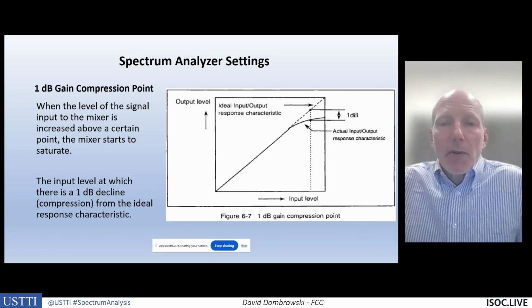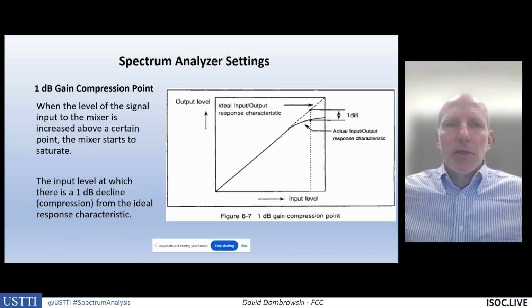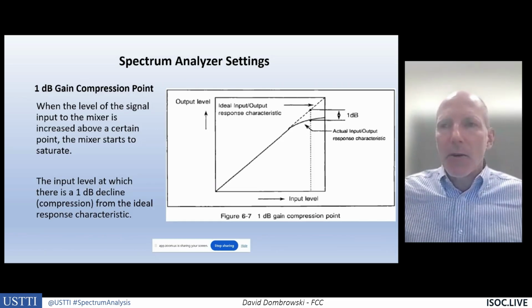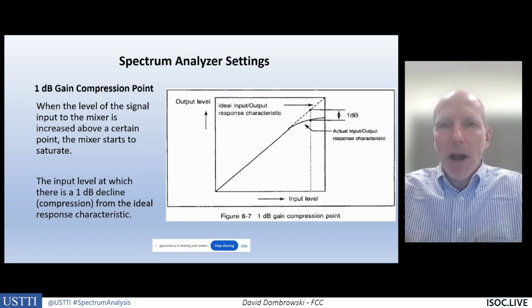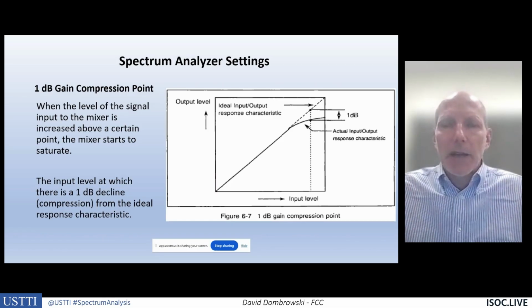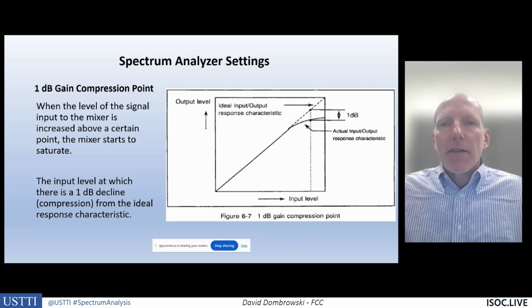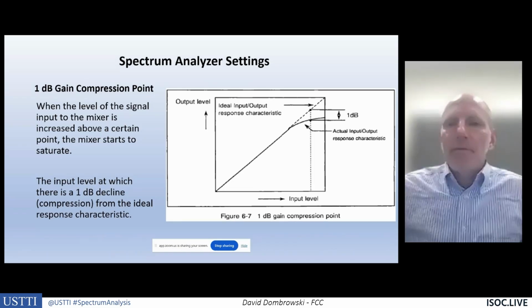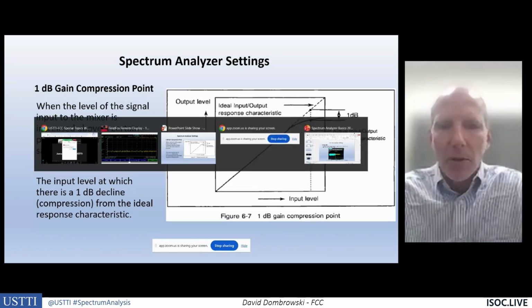And if you're looking at a specific band, it's good to expand out because those adjacent bands that you may not see on the display are still coming into the analyzer being processed. And so it's good to span out the analyzer, look to see what's on either side of you. Are there really strong signals? If there are, let's reduce them with some attenuation so that we are not overdriving our amplifiers and going beyond the 1 dB compression points.